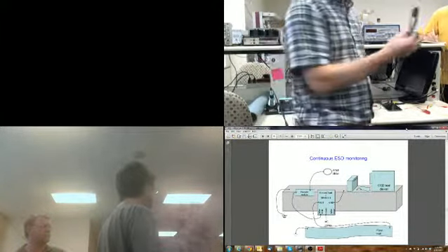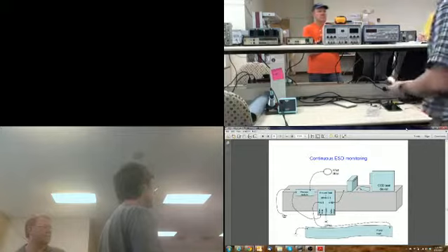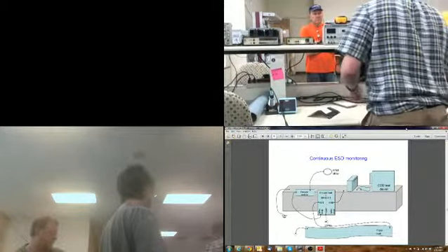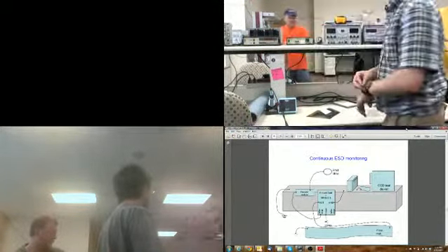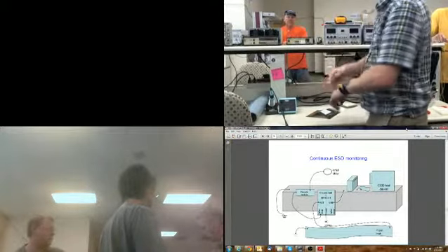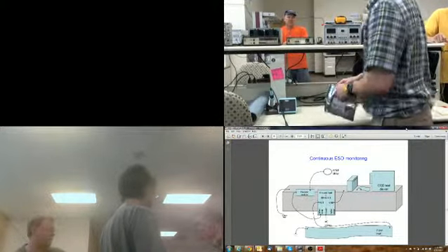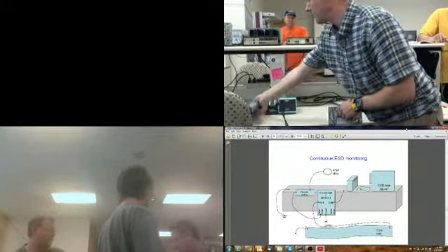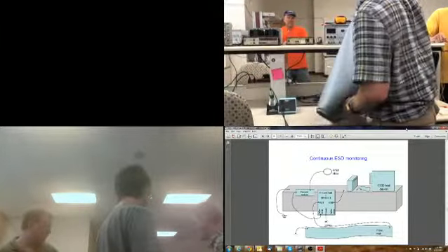So you're generating electricity. Now you move it to your next workstation. You put it down. You put on your wrist strap. You sit down. You make sure you have a mat down that's grounded.